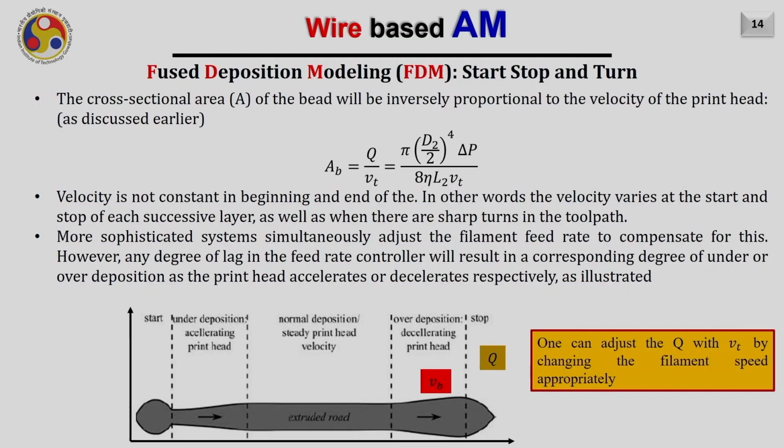If this heat transfer coefficient is low, then of course for a longer period of time the deposited bead will remain at a high temperature, which will allow the bead to form a bond with the neighbor beads, and therefore the overall strength of the part will increase.